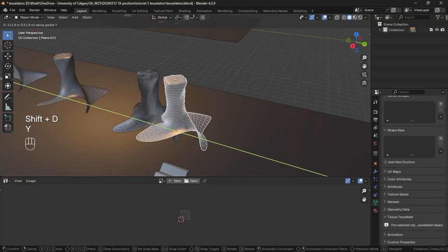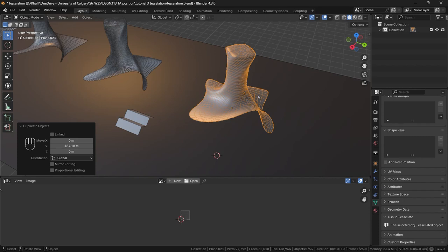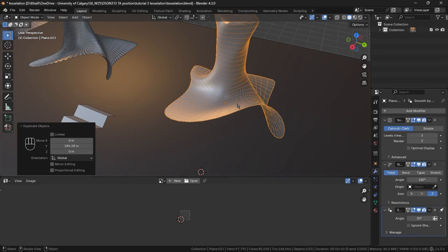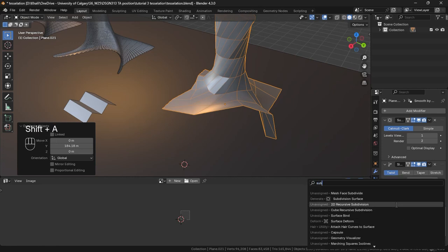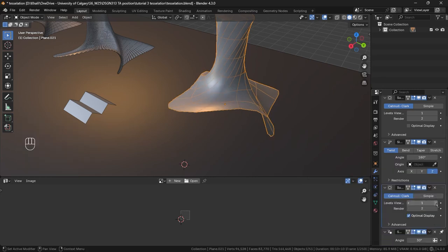I'll duplicate this one and now we'll apply multiple patterns following the curvature. So we will have one subdivision for the curvature and one subdivision for the faces. I'll explain it. For this subdivision here, I would lower it. If I lower this subdivision, I cannot have a curvature. If I want to have a curvature, I need a second subdivision and we will apply a different tessellation, not the quad tessellation we applied now. So this second tessellation will be the curvature.